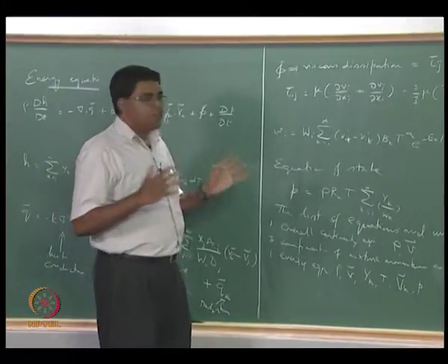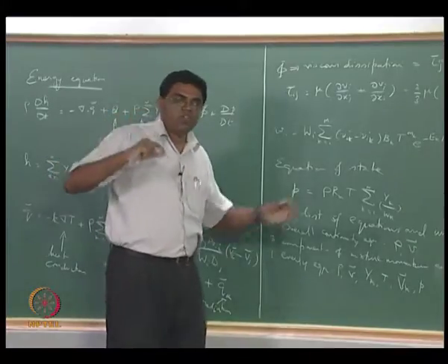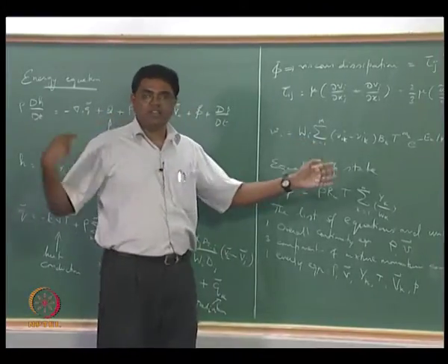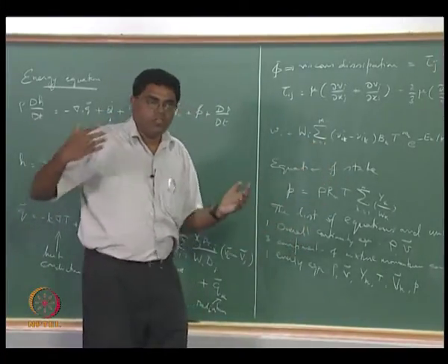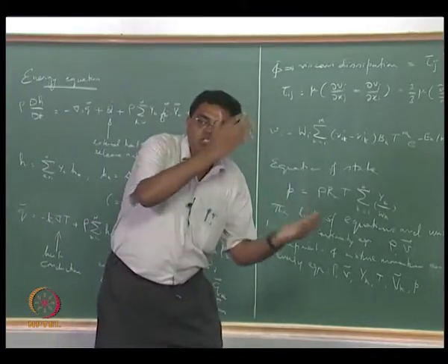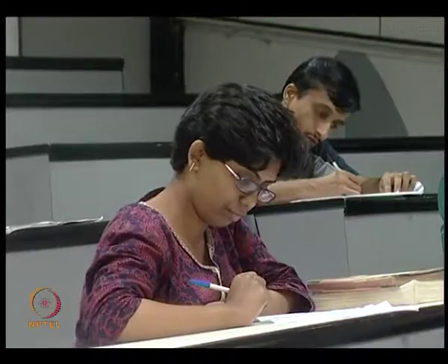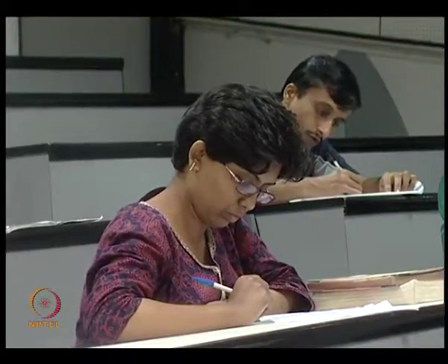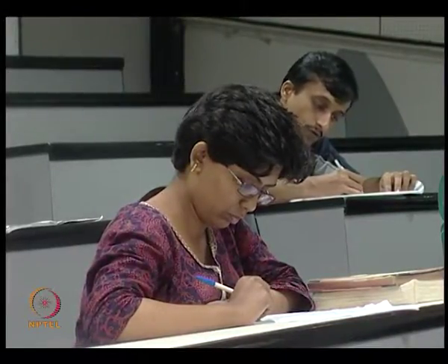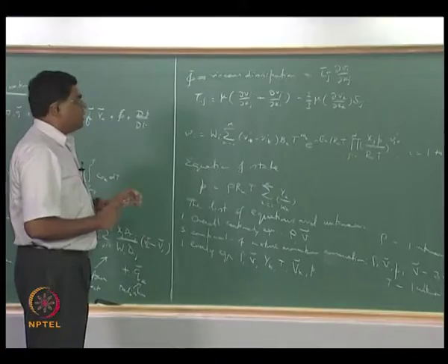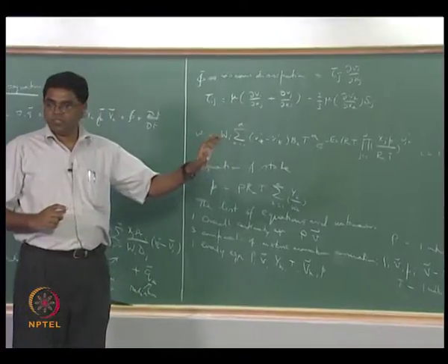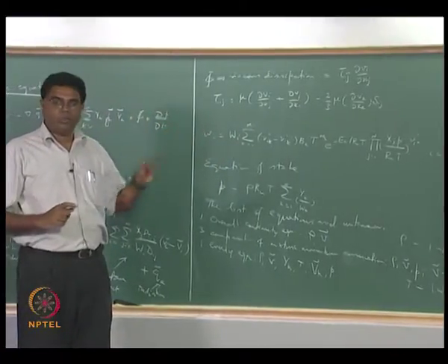So you don't have to worry about taking small time scales to resolve this and the fluid mechanics simultaneously. The fluid is not going to take these species too far from where they are as they are changing because of chemical reactions, so you can freeze the flow during this time. So you can take these kinds of approaches to simplify your life, but life is certainly complicated if you look at the full combustion problem.